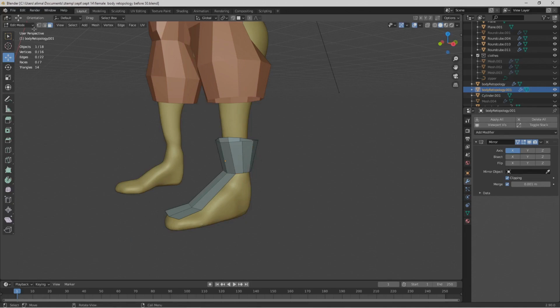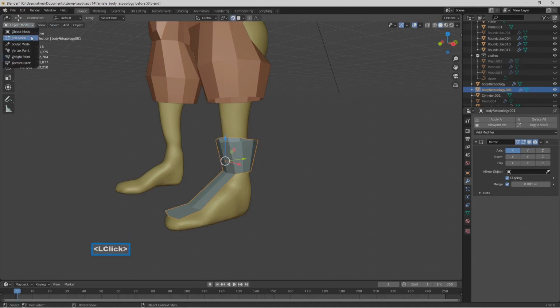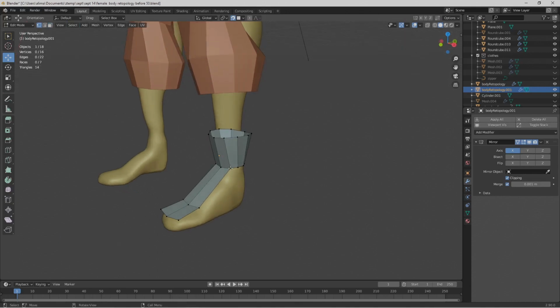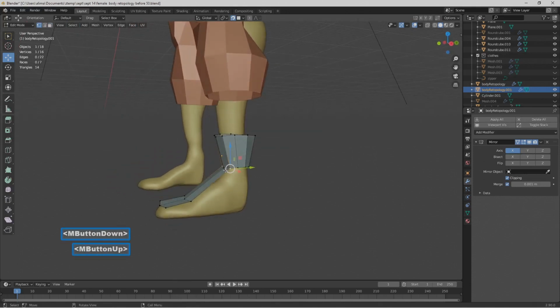Okay, what we're going to do is go to the upper left, go to object mode, turn on snapping, go back to the upper left, go to edit mode, go to vertex select. I'm looking at these two faces, this edge right on the side here, I'm selecting there. I'm thinking I want faces that come down like this, and then another row of faces that go like that.